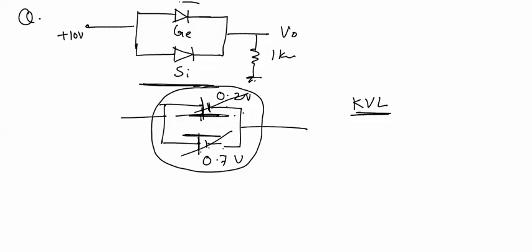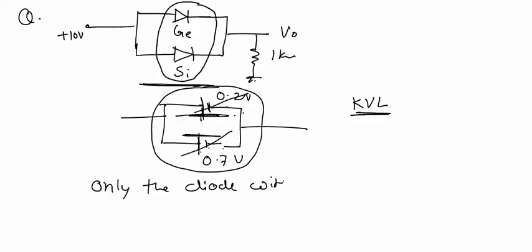You can remember this concept for solving any other problem: if two diodes are connected in parallel, then only the diode with the lower cut-in voltage will conduct.